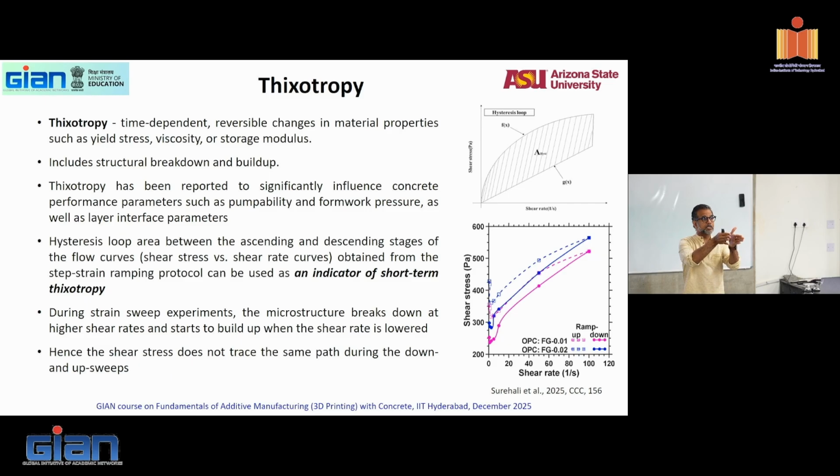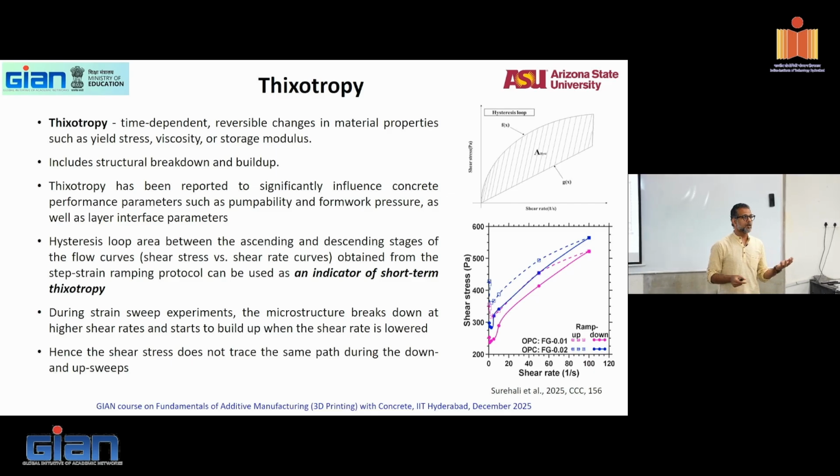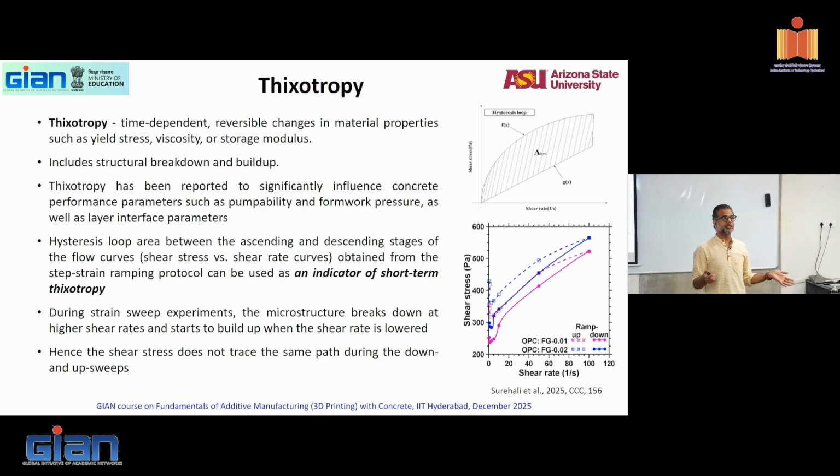So if your formwork is not very strong, a liquid-like material will fail. And you should have heard examples of grain silos failing when you put in a different grain than what the silo was designed for, because of the differences in pressure that it was not designed for. So again, the idea of formwork pressure.